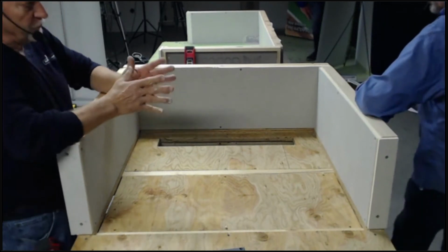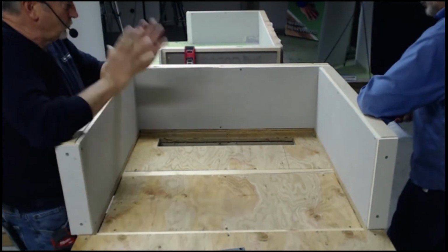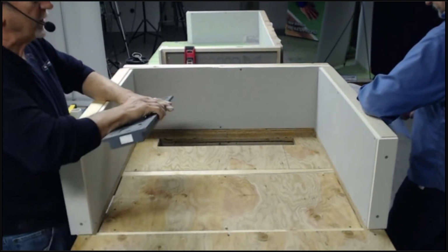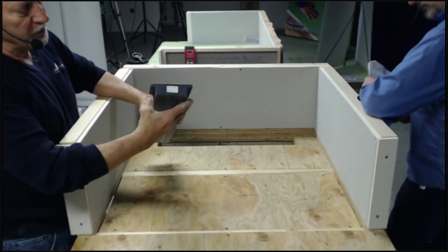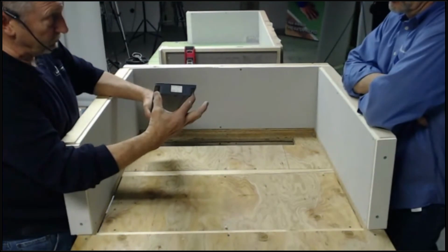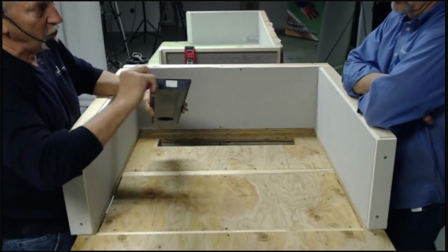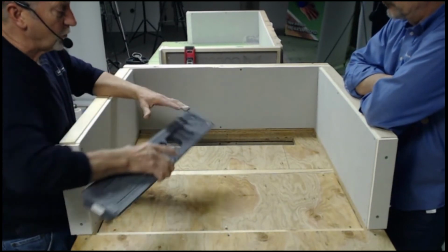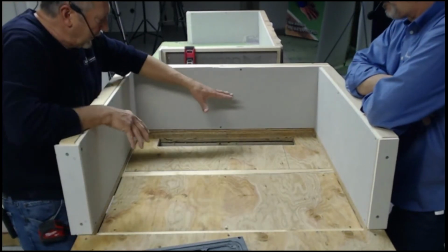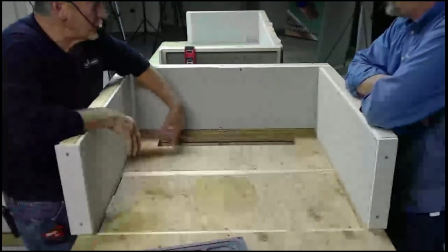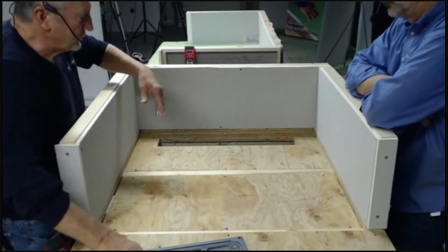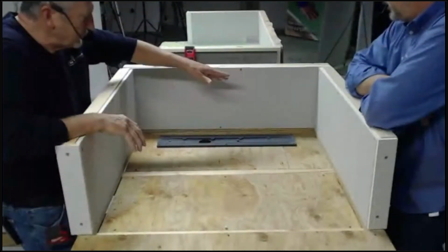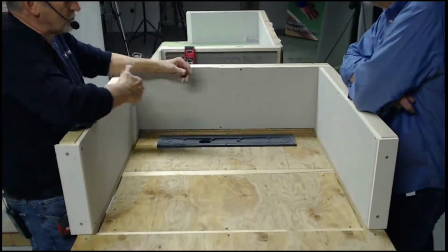So in this case, my floor joists are running parallel with my shower. With the Noble Company freestyle linear drain, our drain has a 3.5 inch body, but it also has these 3/8 tall lips around the edge, which are really supportive. They'll support the whole drain. So if I have the opportunity to have them parallel, I can cut that 3.5 inch by whatever length the drain is and simply drop the freestyle linear drain right in. It's supported by the flange or the wings, so there's no extra structure that you have to put under the drain.